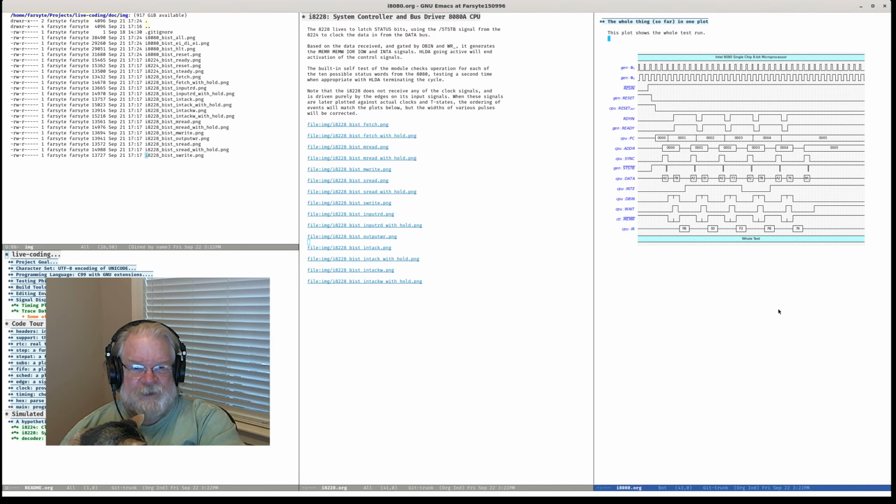All I wanted was a UART that handled RS-232 serial connections, asynchronous serial. So we're sending start bits and the data and maybe a parity bit and maybe stop bits, and that's it. And I wanted to talk to a teletype at 110 baud. I wanted to talk to a modem at 300 baud, that sort of thing.